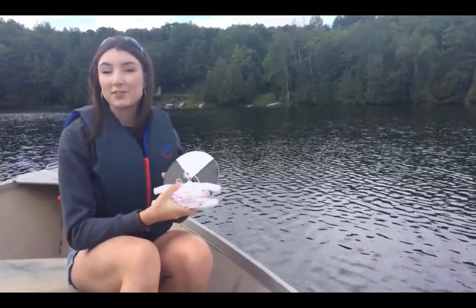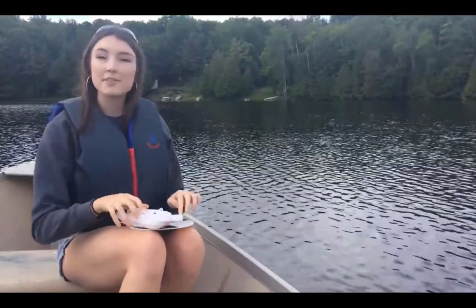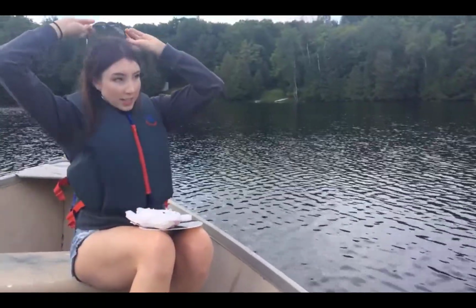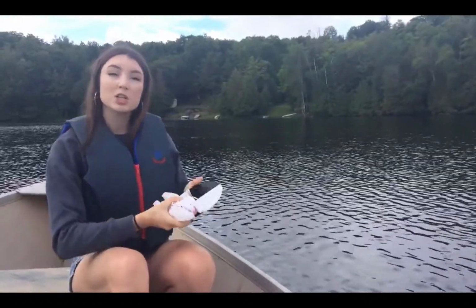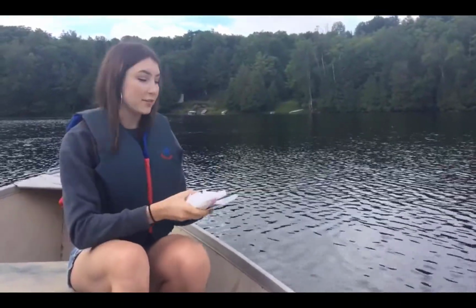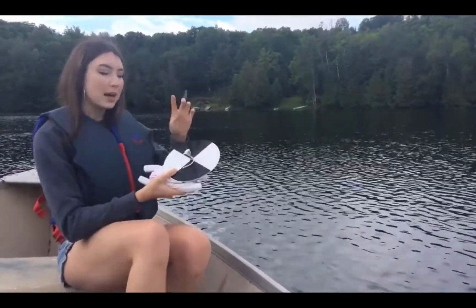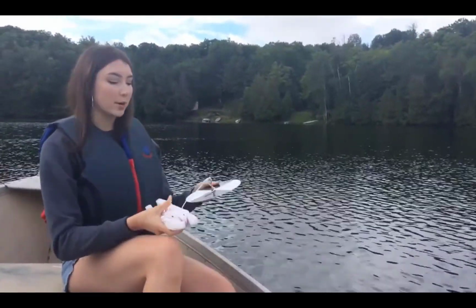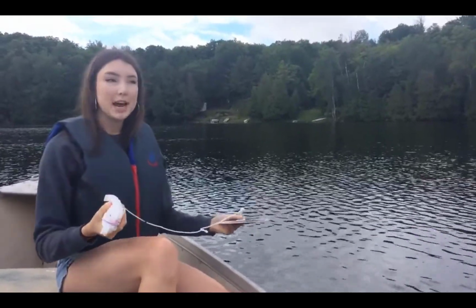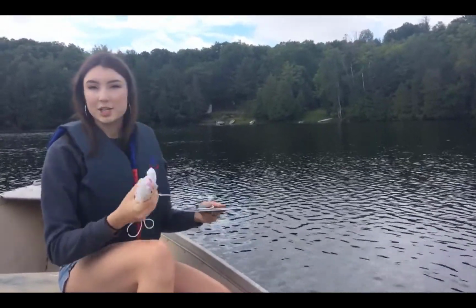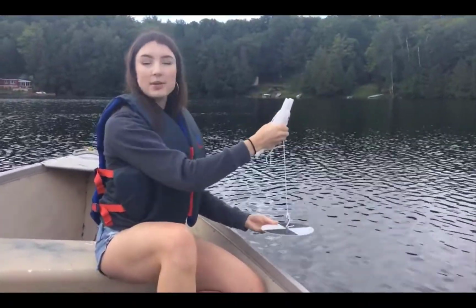So this is our test for Secchi depth, and we use an instrument called a Secchi disc. So again, for this test, we make sure that we're not wearing our sunglasses, and we're going to be doing the test on the shady side of the boat, just because we don't want the sunlight obstructing our view. As you can see, the disc has 2 white and 2 black portions that are easy to see in the water. The most important thing about this test is that as you're lowering it down, especially for conditions with moving water, you want to make sure that the disc goes straight down as much as you possibly can get it.